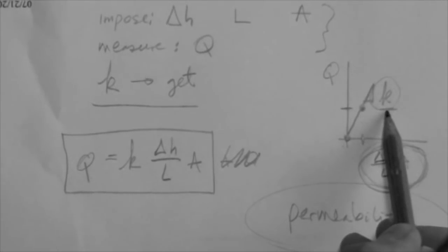But we generally use, that is we, geotechnical engineers, we use both words to describe the hydraulic conductivity, both terms. So the correct one is hydraulic conductivity, okay? But generally, we also use the word permeability for hydraulic conductivity, even though it's not really the same thing. Now you may say, okay, why are you saying all this? We should use the correct name, right? And that is true. We should use hydraulic conductivity for this K.